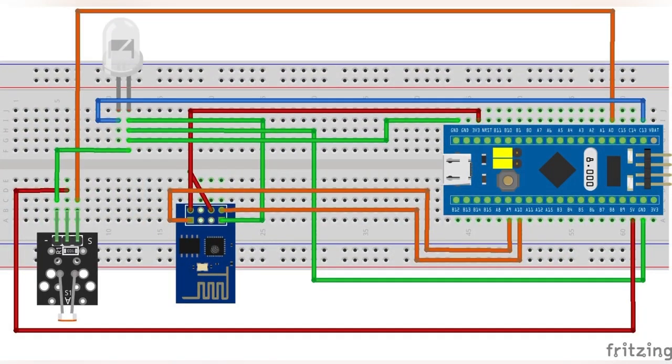Hi, my name is Hidayah binti Halim, and I will explain further about designing and developing this system. This is the schematic diagram for this home outdoor lighting monitoring system that is connected with the STM32F103C8 board, or called the Blue Pill board. As shown in this diagram, the LED is connected at pin 13 of the STM32 board, and the LDR sensor is connected with pin A0. And lastly, for the Wi-Fi module ESP8266, the RX is connected to pin A9, then TX is connected to pin A10 on the board.